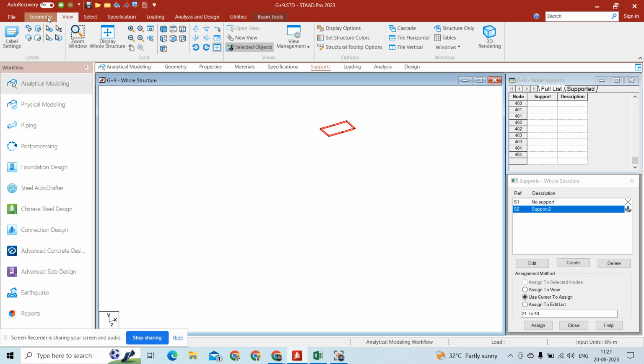We have to keep in mind that for a lift block headroom two parts will come, one for the machine room and another for the roof head. So I will provide the machine room at 1.7 meter height.